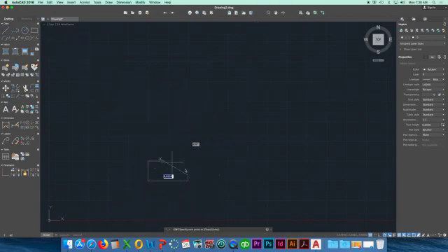Once you get your side view or profile view done, click on the line tool again, and it turns off your line. I am again going to go on the line tool, but this time I'm not going to click on this point. I'm just going to go where the endpoint is, and to the right, go about 1 inch away, and then click. So the width of the front view is 1.5 inches. Then you go up, make sure it's perpendicular, 90 degrees, 2.5 inches. Over, again 1.5 inches, and then it connects to the endpoint.